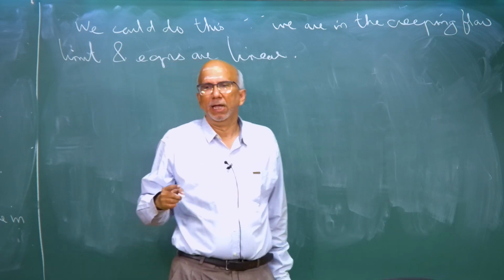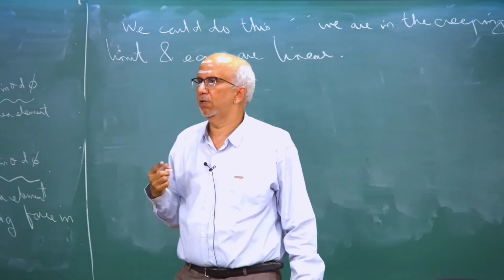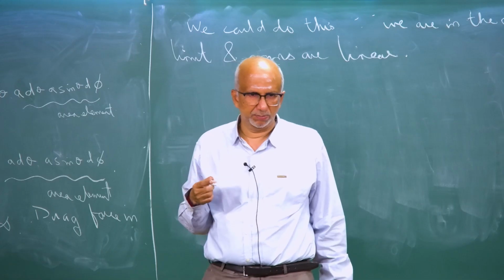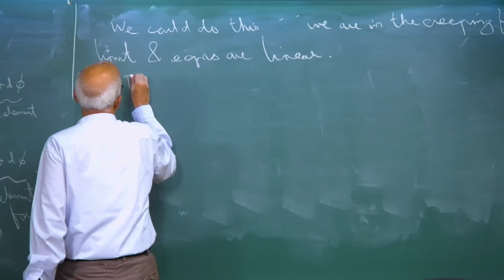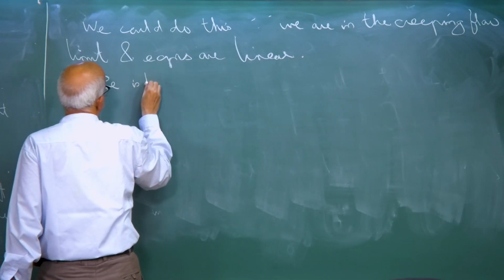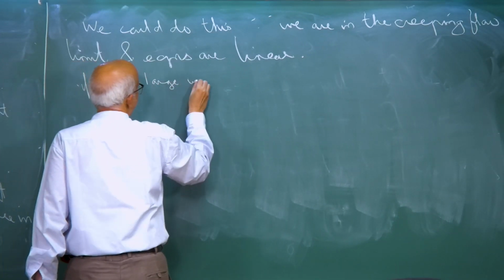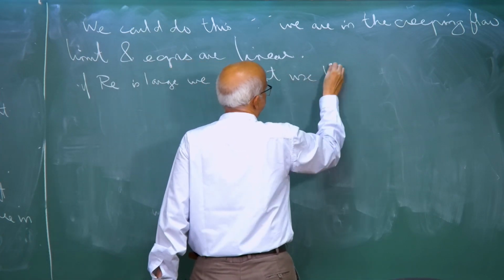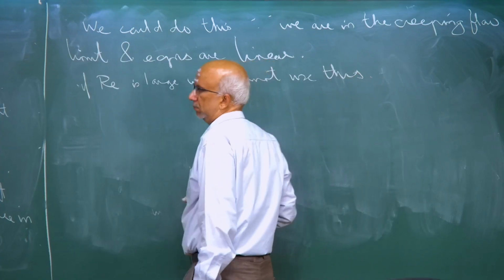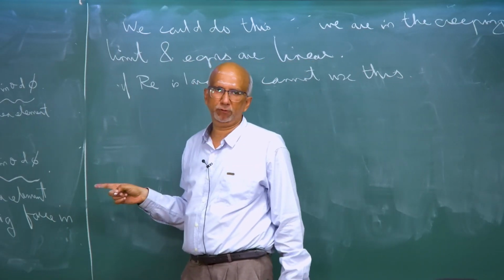Okay. Now, if you are not in the creeping flow limit, if your Reynolds number is large, we cannot use this. Okay, this expression for drag force cannot be used.